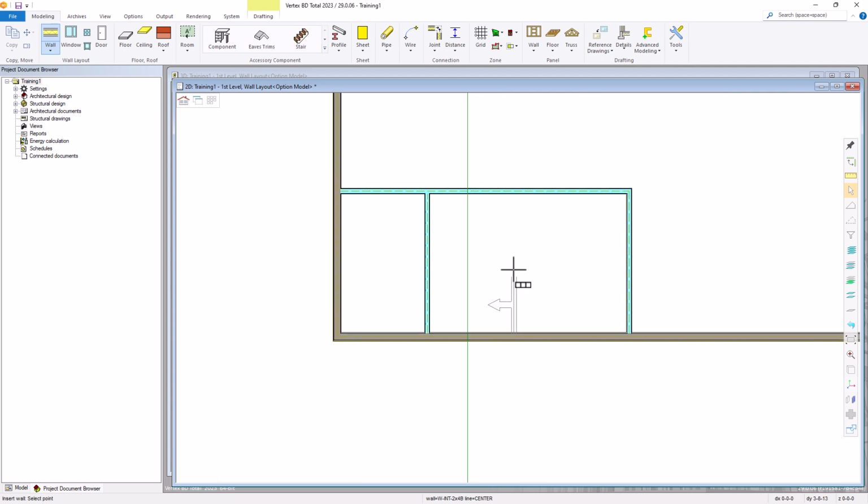And this time I'm just going to go up, and let's say I want this wall to end in line with the middle of this wall. So I'll just pick that midpoint, and that's as far as I want to go, and hit V to confirm. Let's go ahead and add one more short wall segment off the midpoint of this wall. Lock it in horizontal, and let's just go over, let's say 3 feet for now. And V to confirm. We'll hit escape to end the wall segment.